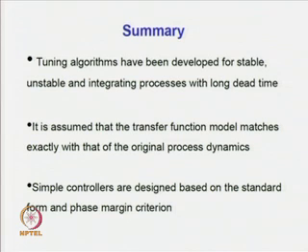It is assumed that the transfer function model matches exactly with that of the original process dynamics. This is one of the major requirements we have for our analysis and controller design, and to design a robust controller, we need to relax this condition.